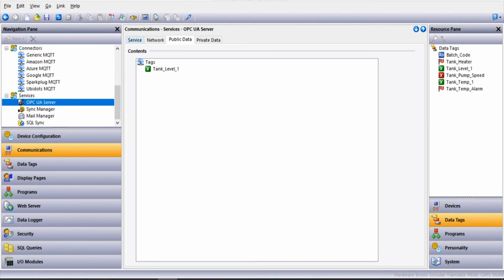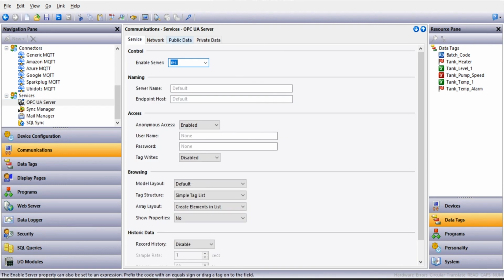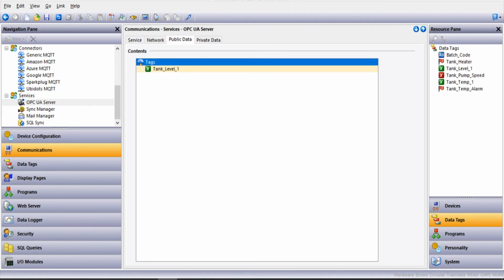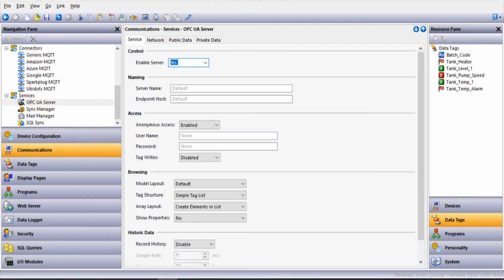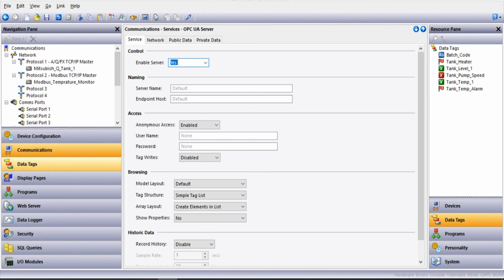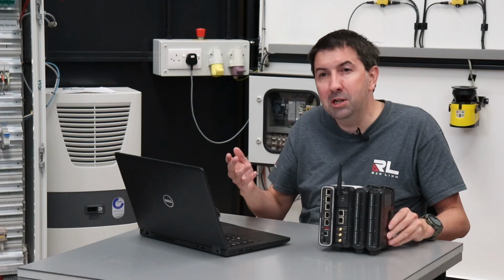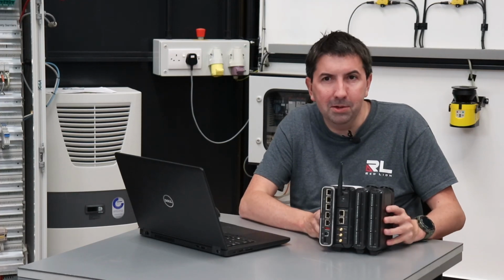I'll do OPC UA, and as you can imagine, if we go to it, we allow it, we take in the data we're interested in, we drag and drop our data in there. I can add more later on, I'll add if the pump is on. And that data will be published by OPC UA. But to go into detail on that later, and to go into detail on setting up tags, we have other videos. Additionally, what we can also do is back up onto a memory stick.